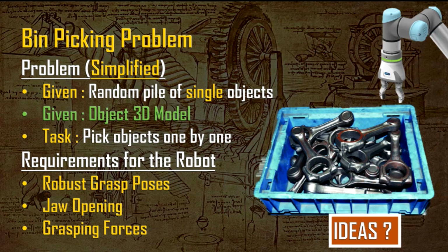Yeah, a bit on that, but I have this one doubt. Every time, the heap will start reducing, like when we pick, we drop, we pick, we drop. Then it will go deeper, and the joints have to turn deeper to pick the objects. So the distance of the objects from the camera will start varying, right? It will increase. So do we need a depth camera over here, or depth knowledge? How exactly are we going to determine that?